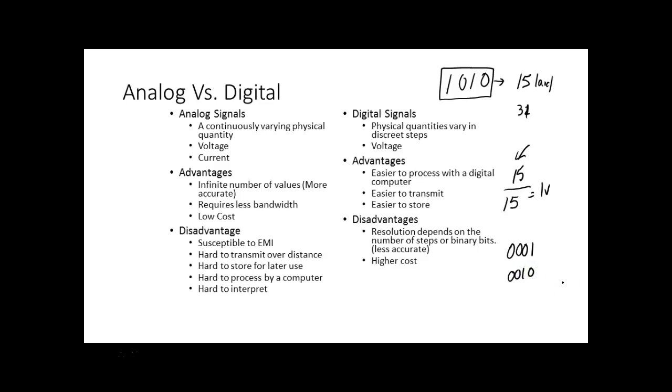If my sensor gives me 2.1 volts, I can't represent that, right? You understand that? If my sensor gives me 18 volts, I can't represent that either. I've exceeded the range. So here our resolution would be 1 volt. That would be the resolution. So we couldn't do fractions. We couldn't do a lot of things. So the more bits I add to my analog to digital converter, the better the resolution is. That makes sense? Yes or no?